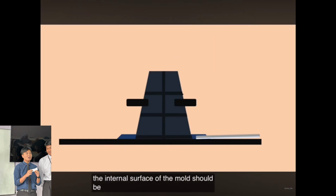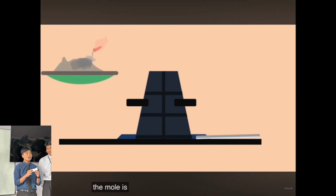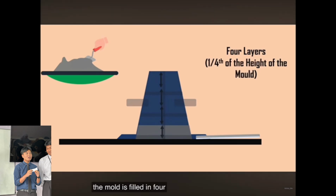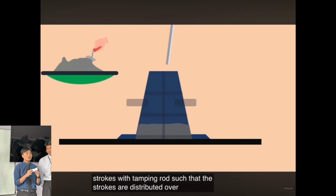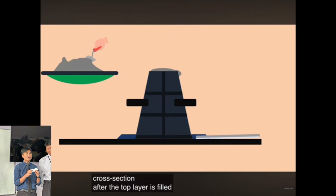The internal surface of the mold should be thoroughly clean and free from moisture and any set concrete before commencing the test. The mold is placed on the smooth metal plate. The mold is filled in 4 layers, each approximately 1/4 of the height of the mold. Each layer should be tamped with 25 strokes of the tamping rod, such that the strokes are distributed over the cross-section. After the top layer is filled, the concrete is struck off level.